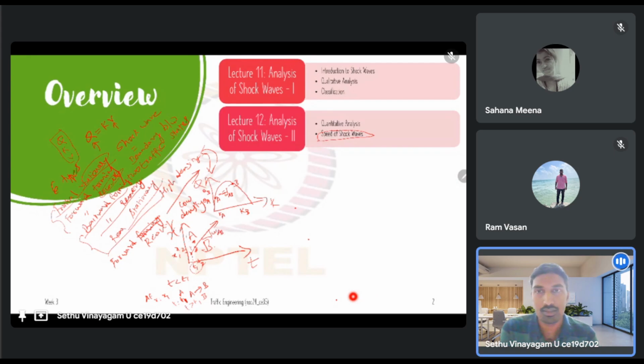So how did we get this? We looked at it in the lecture. It's basically coming from the conservation of flow along this shock wave boundary, right? So the number of vehicles that are moving. So what is happening at the boundary? As I said, immediately upstream of it there is traffic state B, and immediately downstream of it there is traffic state A, right?